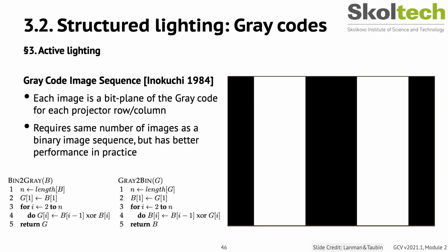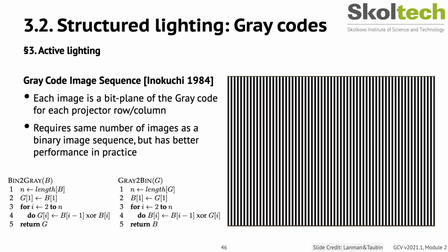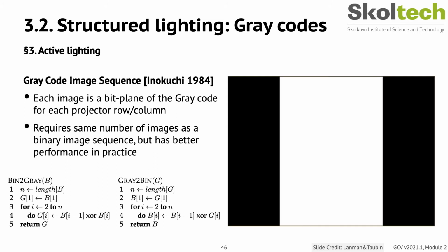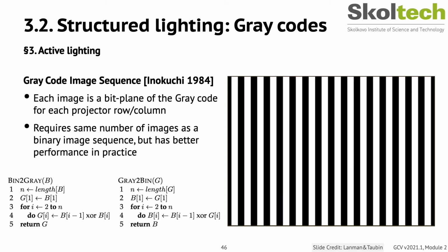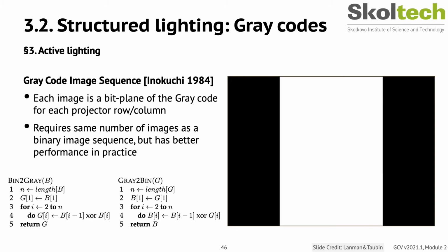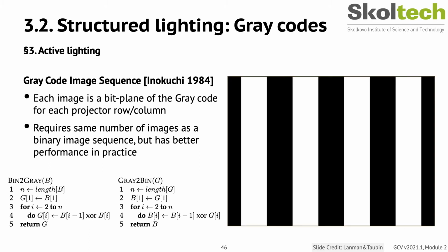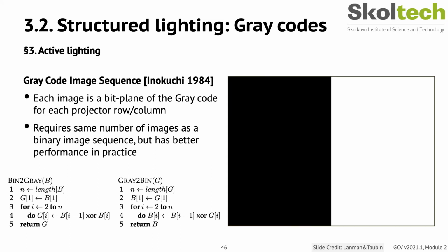Considering the projector-camera arrangement as a communication system, a key question arises: what binary sequence is most robust to the known properties of the channel noise process? At a basic level, we are concerned with assigning an accurate projector column or row to camera pixel correspondence. Otherwise, triangulation artifacts will lead to large reconstruction errors.